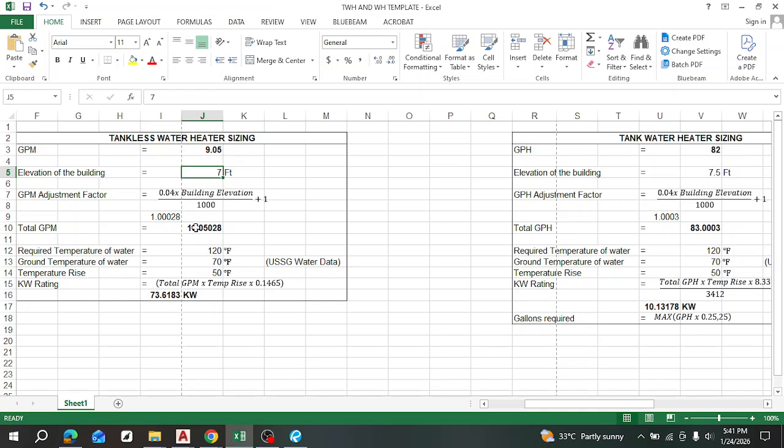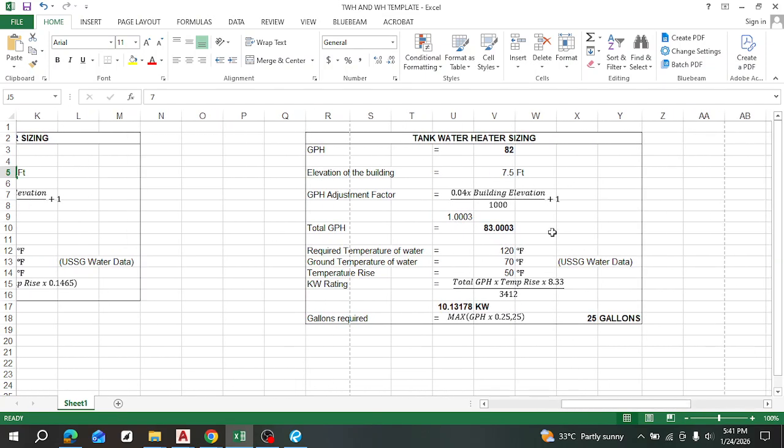So as I was saying, the main factor you use is to get the amount of flow rate that is needed, the maximum flow rate that is usually needed, which is this. And this is because we don't want to undersize, right? If you undersize the water heater, you will not be able to meet the demand. I've showed you how to do all of that. So in this case, this is it: the maximum demand at a time. And this is also the amount of energy required to heat it.